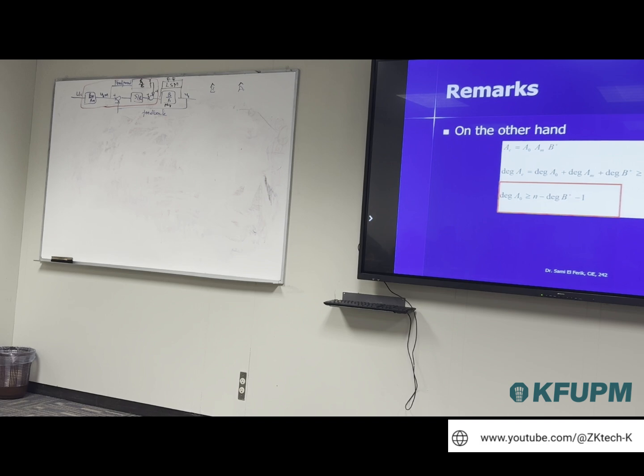Yes. All right? So the inverse model, we are using it to close the gap between Y and YM. And then the feedback is taking care of any errors in the estimation. And we understood yesterday that if I design my controller by inversing the dynamic, when I say my controller, it means I design R and S and T by looking to the inverse of the zeros that are bad, then S over R would be unstable and the system would be completely unstable. Is it clear what I said here?